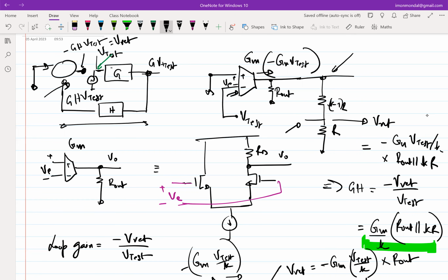Okay, good point. So we don't have bandwidth to go there. So his point is, if there is a circuit where you cannot avoid this, for example, where there is no position where you can effectively break it without affecting loading, then what do you do? You can break it anyway, but in that case, you have to put back that loading effect.